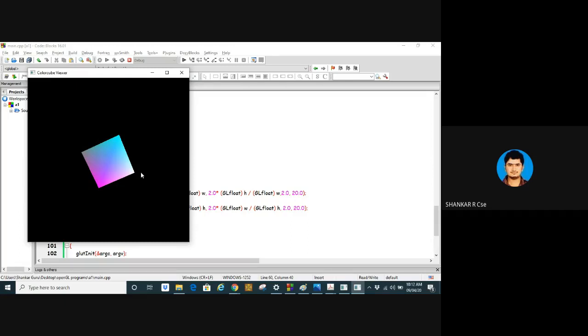Now there is one more extension called keyboard. Now look here, please. This is where perspective projection really comes into the picture. Perspective projection means natural projection. If I press small x, with my caps lock off, you can see the object goes far away, like a one-point projection. As the object goes far away, it looks very small.